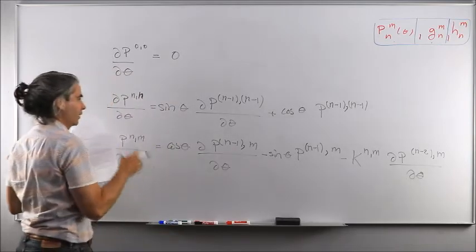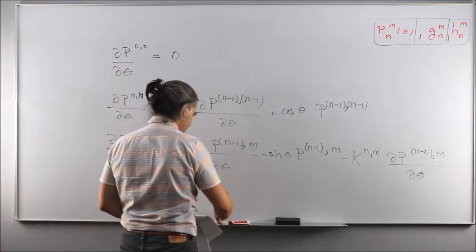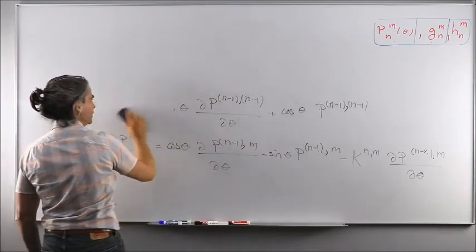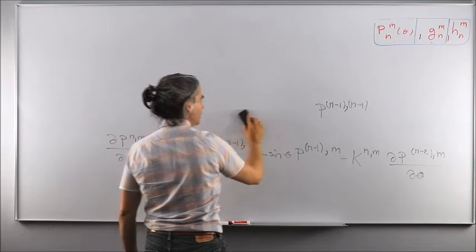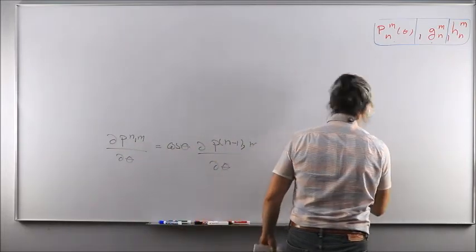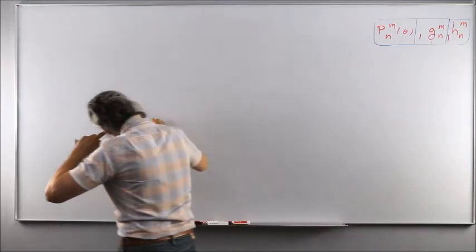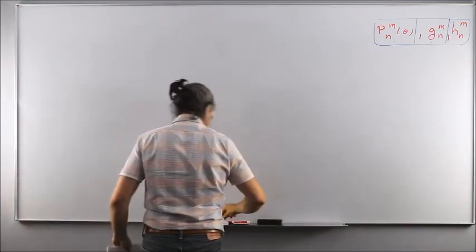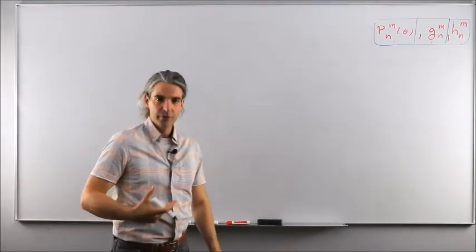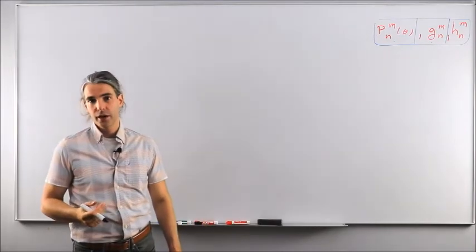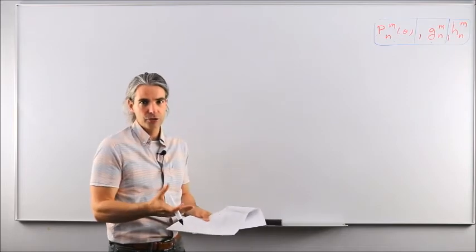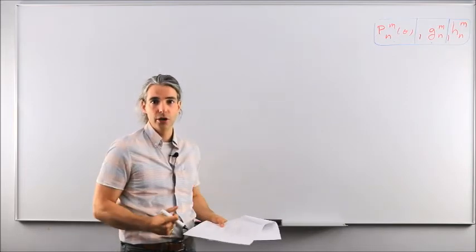But doing so, plugging this back into BR, B theta, BZ, does not really give us what we need as an engineer to simulate the rotational motion of the spacecraft under the influence of the gravitational perturbing torque. Correct? Because what we need is the components of the magnetic field of the Earth in the body fixed reference frame. So it'll make more sense, such that we obtain the torque in the body fixed reference frame and use that practically in Euler's equation of motion.